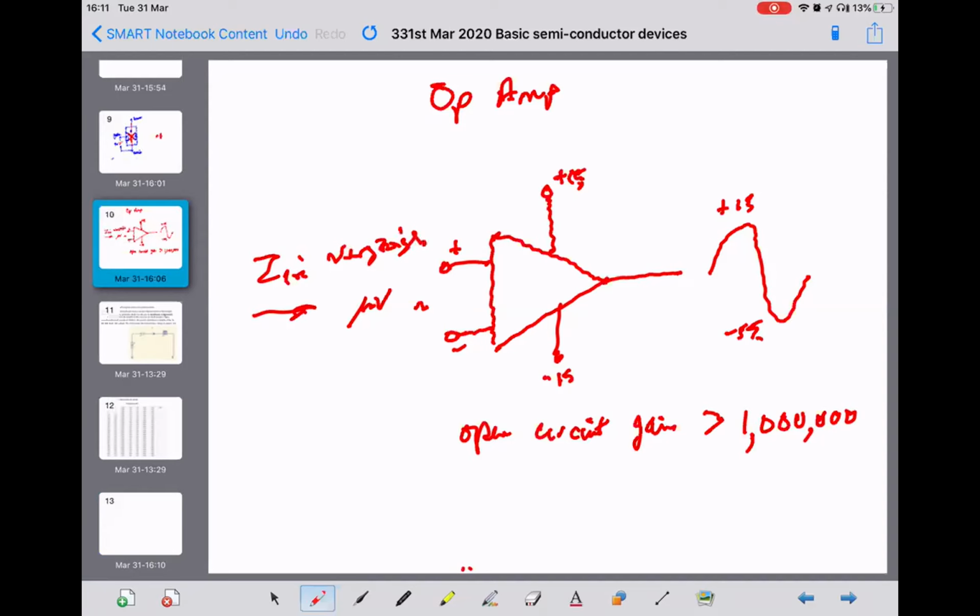That means it doesn't draw very much current from the device that's connected to its input. So microamps, yeah, and it has a low output impedance, so it transfers well to the circuit it's transferring into. All right. At that level, its action, that's what you need to know, is that it amplifies the difference between these two terminals, marked plus and minus.